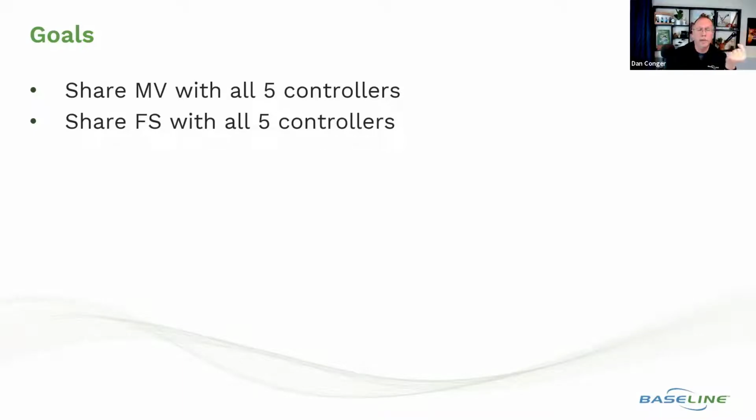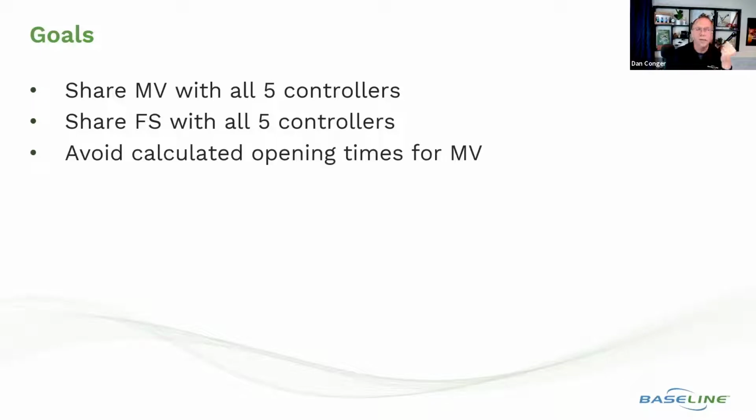Now we could change out the master valve for a pump station, but we don't want to do this calculated opening time for the master valve. From being a contractor, I've done this before. It's like, well, I'll leave the master valve open during this time when all the controllers are going to run. Or to Andy's point, maybe I run this controller on Monday and this on Tuesday. That's a bunch of baloney, right? And if it's a normally open, normally closed master valve, you're just trading problems, right? When do I open the master valve? When do I close the master valve? There's really no gain on there.